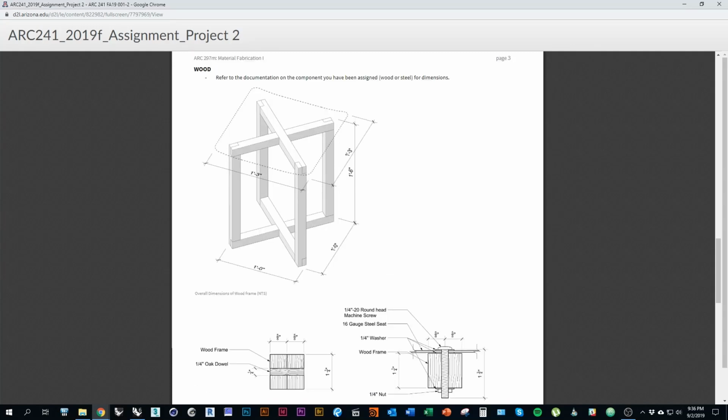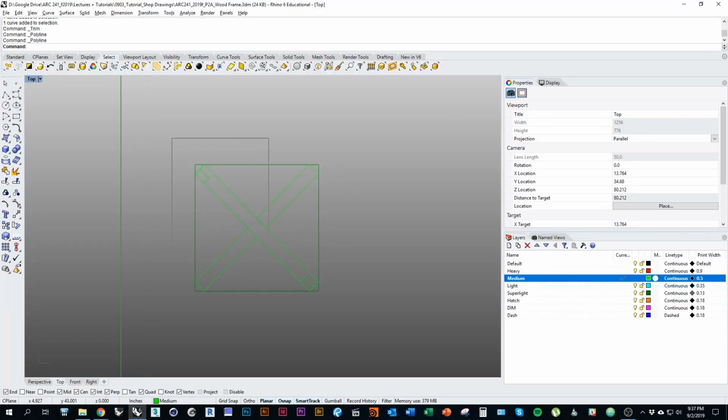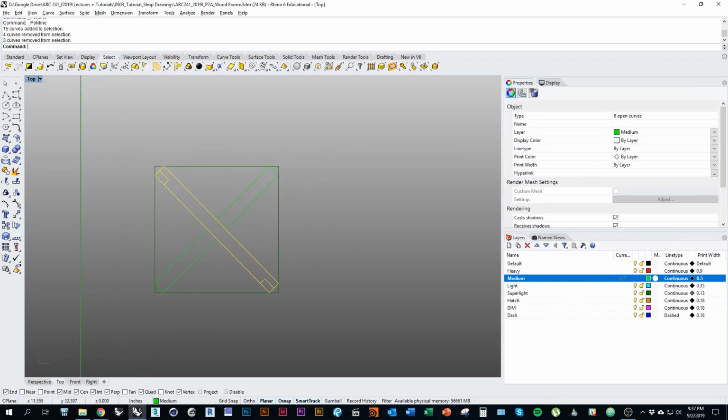And what I mean by that is, if we look at our stool design, if we're careful about how we choose the placement of what side each joint is cut on, we can actually get away with only making two different parts. What that means is we can design the stool so that the way that we would cut this part out when we're fabricating is exactly the same as how we would cut this part out. And that's really good because it's going to make it a lot easier for us to keep track of what cuts we need to make and where they need to be located on the pieces, and just avoid making mistakes while we're fabricating. So what I'm going to do is select this line right now, just to demonstrate how to use this one as a template.